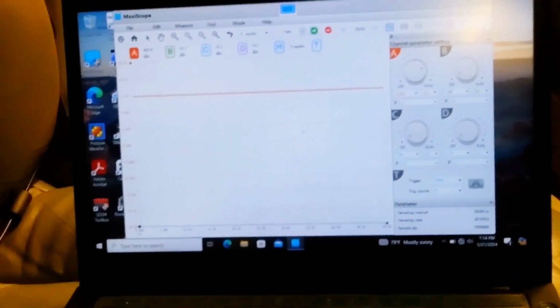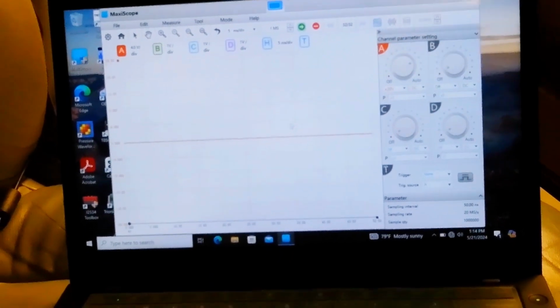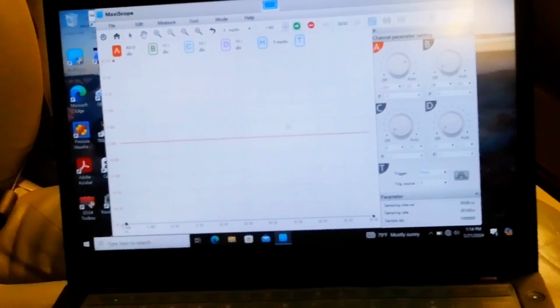Okay, you can see we've got good voltage, we've got good ground supplied to the module, we've got a good signal coming out of the HVAC control head. We've got everything this module needs. We've got good connection through the blower motor. The windings are good in the motor, but it's not finding its path to ground through this module.